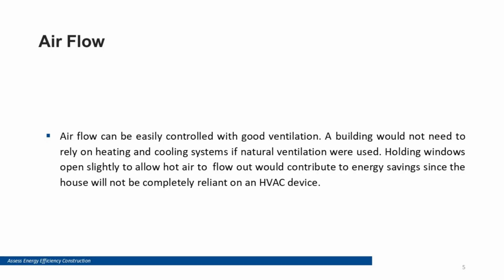Air flow. Uncontrolled air leakage increases heating and cooling demand and carries moisture into cavities. Air tightness is achieved through continuous air barriers, sealed penetrations, and careful junction detailing. Fresh air is then supplied through planned ventilation rather than accidental leaks.